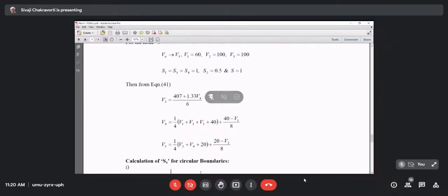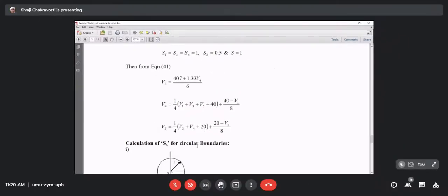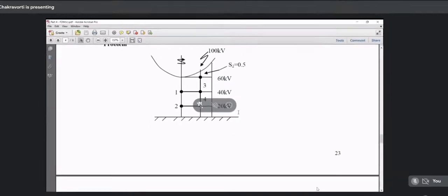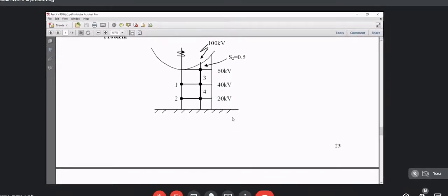Node 4 and 5, here you can see node 4 and 5, they have also equal nodal distances, and so we can use the equation developed in our last class for the node when it is lying away from the axis. Because remember, in an axisymmetric system we will always have two equations, one for the node lying on the axis and one away from the axis.